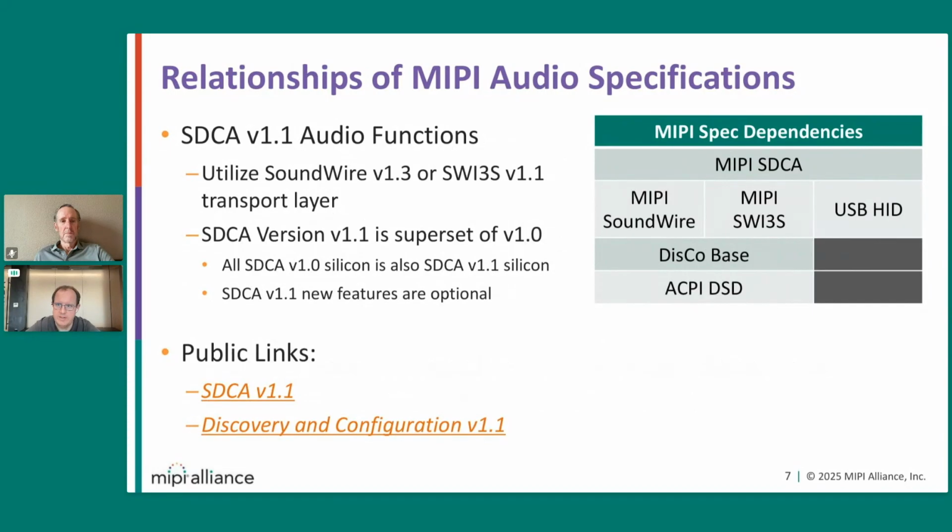So what are those dependencies? MIPI SDCA talks about the audio peripheral functions. Those peripherals can be connected over MIPI SoundWire or MIPI SWIS transports, and which transport is used in a system is fairly invisible to the SDCA function drivers.